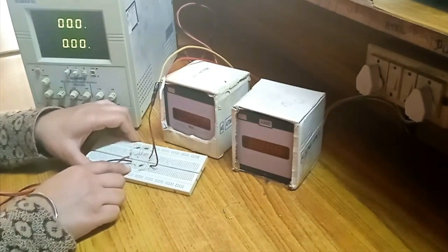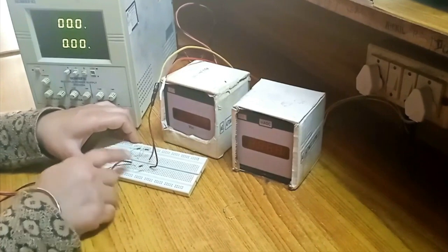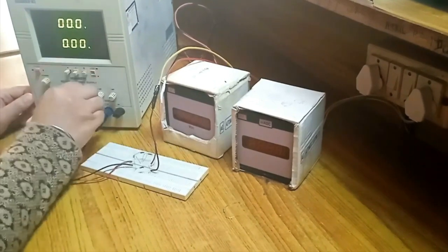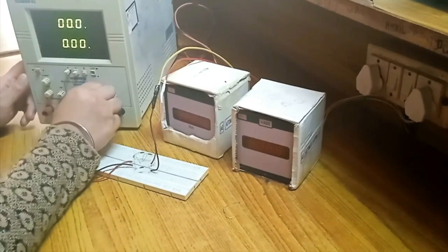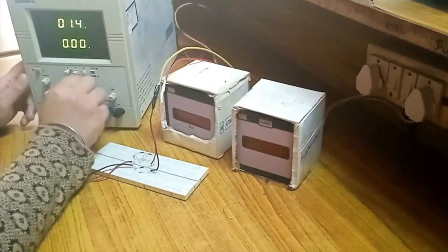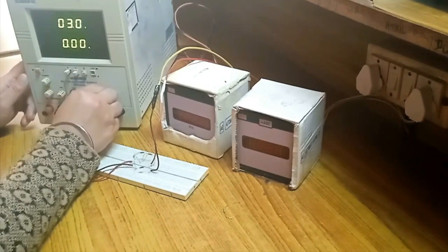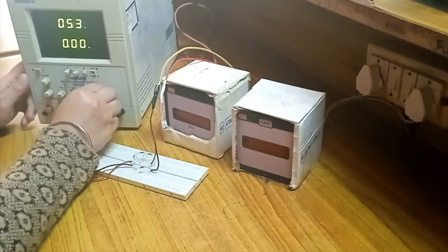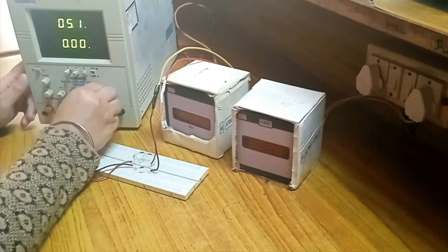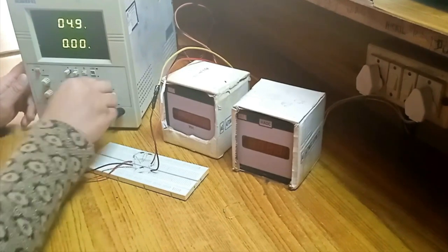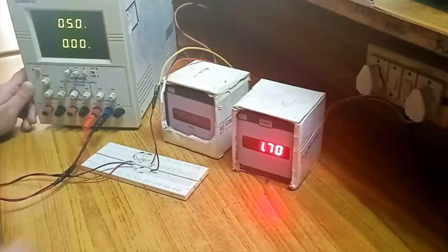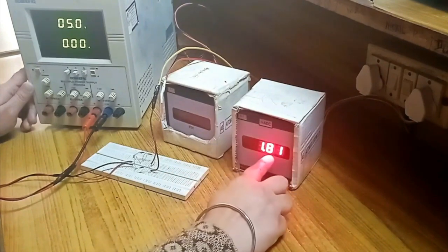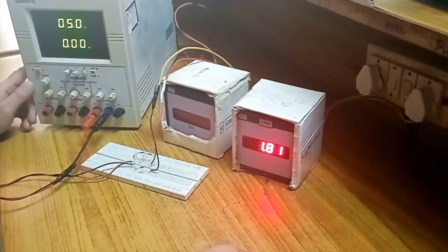So again you can have a look. I have connected all these connections in a single column, and the input must be set to 5 volt. Right now I am using channel B, so channel B must be pressed. So let us increase the voltage to 5 volt. So input has been set to 5 volt. Now let us switch on this ammeter. So you can have a look. We have got around 1.81 milliampere as the step number 1 IL flowing through RL.